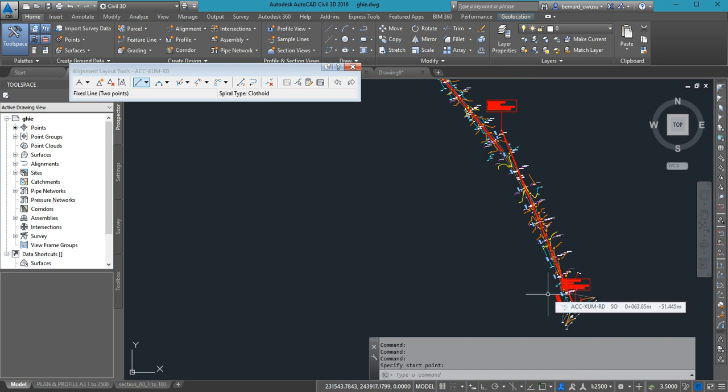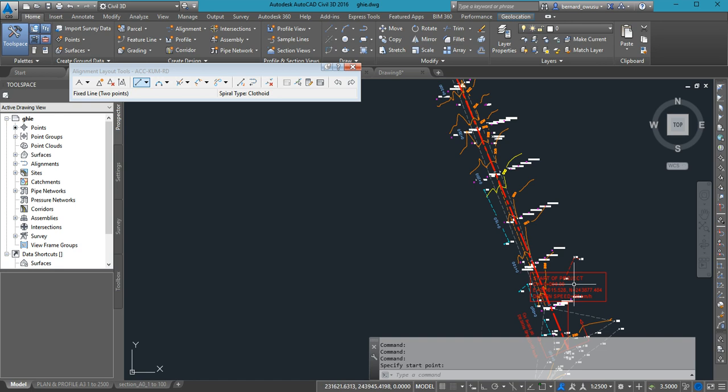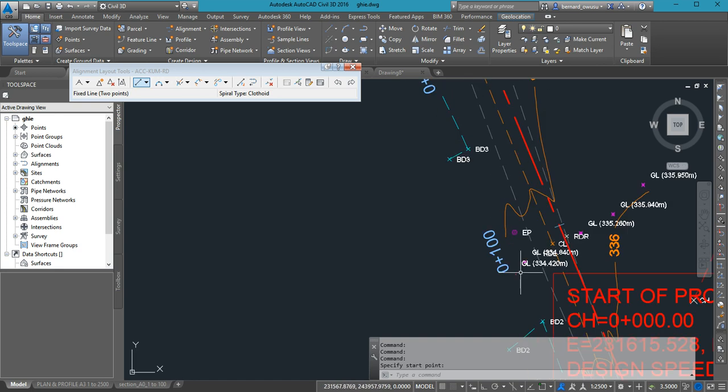Now, before we do that, you remember when we started, we said we want to have an idea of our road width. And we came up with 14.3. So 7.15 to the left, 7.15 to the right. Is that not it? Good. So what we are going to do is define something like a boundary, an offset, running from beginning to the end, so that that will also guide us.